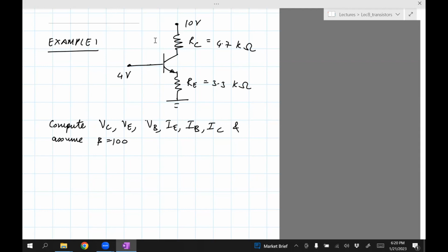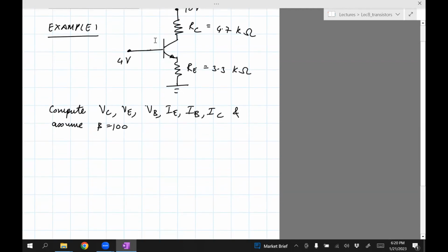don't know a priori if, for example, the diode is conducting or not, but we'll assume it's conducting and then prove or disprove that. And if it's not conducting, then we have to change the assumption and solve it again. In this case, we have to do something similar. We need to assume something and then solve it and see if our assumptions hold true. So here, let's start by assuming that the junction transistor is in active mode, solve the problem, and verify based on the equations I wrote down earlier if it's in active mode or not.